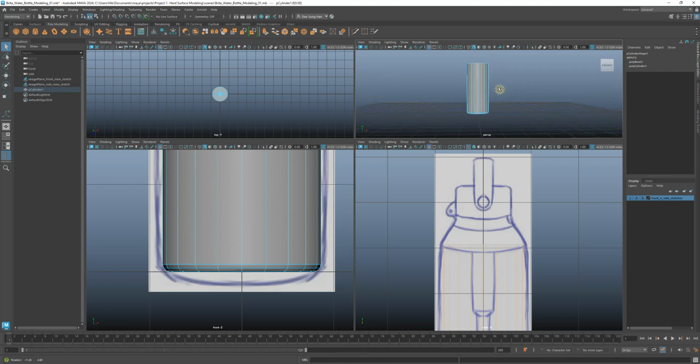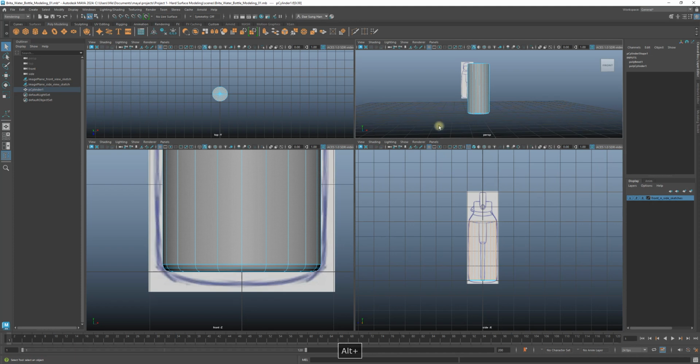But if I have this like this, okay, and I hold on my control key, I'm gonna hold it down, and my cursor turns into a minus sign. When it turns into a minus sign, from down here, I'm gonna left click and hold and drag, and then let go. So it deselected all of that, but it's still selected my top view because I did not marquee all the way up to the top, which would have deselected everything. So I only selected that.